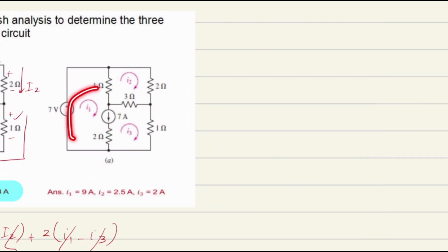So imagine that I write down all of the equations and everything is fine, but I'm going to have another problem because I don't know anything about the voltage of this element. You don't have any resistance, you don't have anything related to that. So it would be 3 equations, 4 unknowns. At this point, it would be better to use another way. And while I'm using mesh analysis, at this point, I have to use loop analysis.